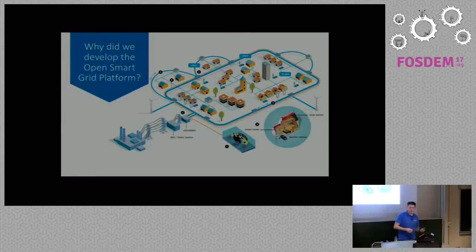One particular example where we needed the Open Smart Grid platform was for switching the public lighting. What we have right now is a technology called ripple control technology, which basically is a big sender who sends out the pulse over the 50 Hertz grid, and then you have devices that pick up that signal and switch on the street lights or switch them off. Not really intelligent. And also municipalities were banging on us: hey, we'd like to have more control over the streetlights. So colleagues were looking into a solution to control all those devices and build an app for municipalities.